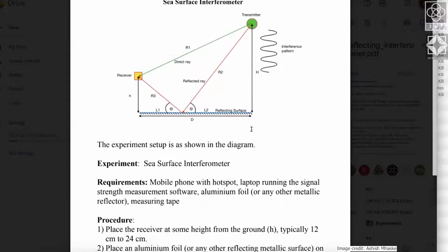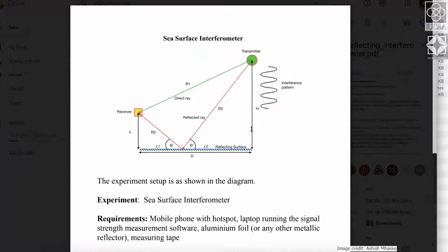During all these experiments, one thing that is required: there is a README file in the folders for the software, and you can go through that file to understand what to use for which operating system. One thing that is recommended in all these experiments is that you do not connect to the internet while doing them, because if you connect to the internet, we see that the fluctuation in your noise, or let's say power, in your measurements is very high.